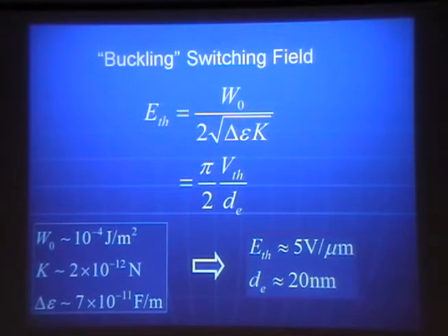So it's an interesting comparison that cell thickness is now compared to the pattern size. And the numerical estimate is as follows, using a fairly strong anchoring energy of 10 to the minus 4th power joule per square meter, which was probably the strongest anchoring energy we can assume.